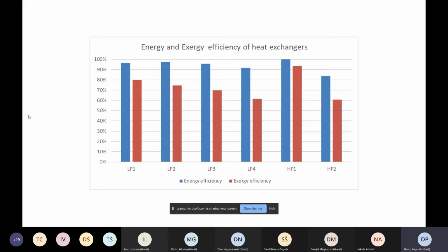Its exergy efficiency is equal to 78%, and its exergy losses are around 22 megawatts. Deaerator, reheater, moisture separator, and steam generator are components whose energy efficiency is almost 100%, so the energy losses are minimal, while exergy efficiency varies from 78% to 98% for the specified components.